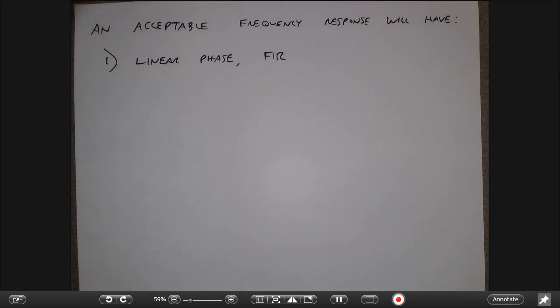Again, we like linear phase filters because the effect is simply to delay the output of the signal, right? And a linear phase FIR filter turns out to have this very nice filter structure, which means that the filter is real and it has symmetry around its middle value. Either it has actual symmetry, meaning like it's kind of even around the middle, or it has this odd symmetry,